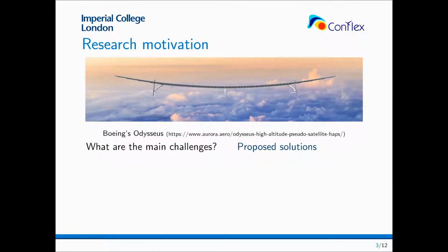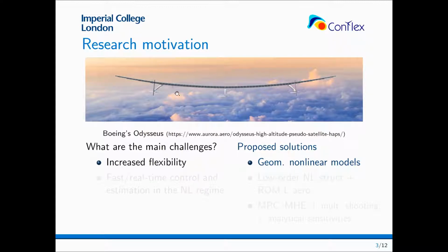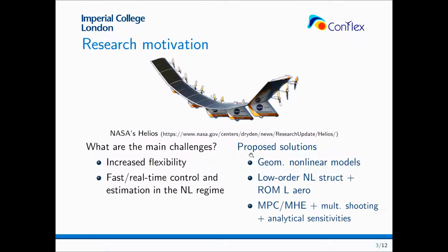Okay, so next generation aircraft, and especially high altitude long endurance aircraft, or high altitude pseudo satellite concepts, are striving to improve aerodynamic efficiency, since they aim to remain airborne almost perpetually. That is done by using ever more slender wings and lightweight composite materials, which has the immediate effect that the flexibility of these airframes is increased. So large deformations can be expected, which necessitates geometrically nonlinear models. Also, when traditional control methods have been applied to these structures, they have been shown to still be very vulnerable to atmospheric disturbances or turbulence. So this has highlighted the need for advanced or novel control strategies.